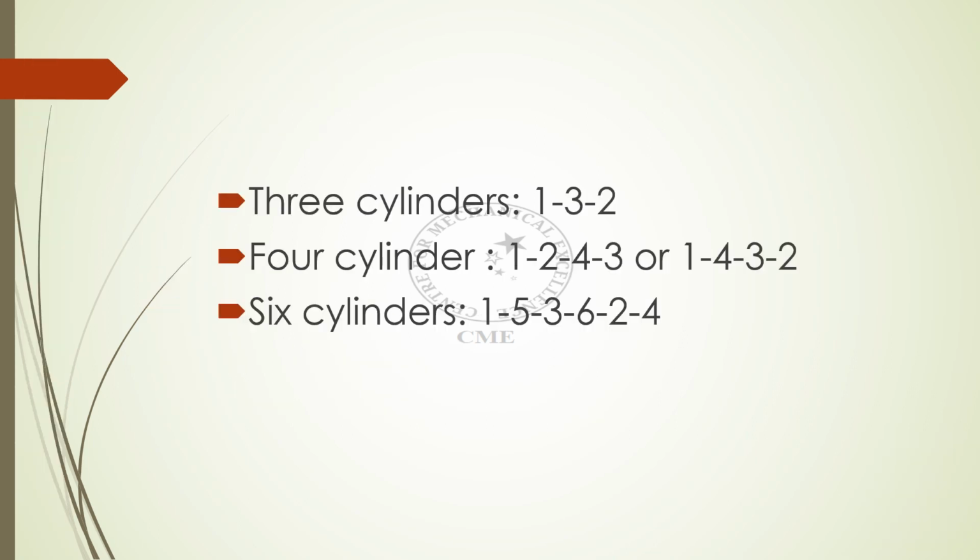In the case of a 3-cylinder, the firing order is 1-3-2. In the case of 4-cylinder, the firing order is 1-2-4-3 or 1-4-3-2. In the case of 6-cylinder, the firing order is 1-5-3-6-2-4. Please remember these things.